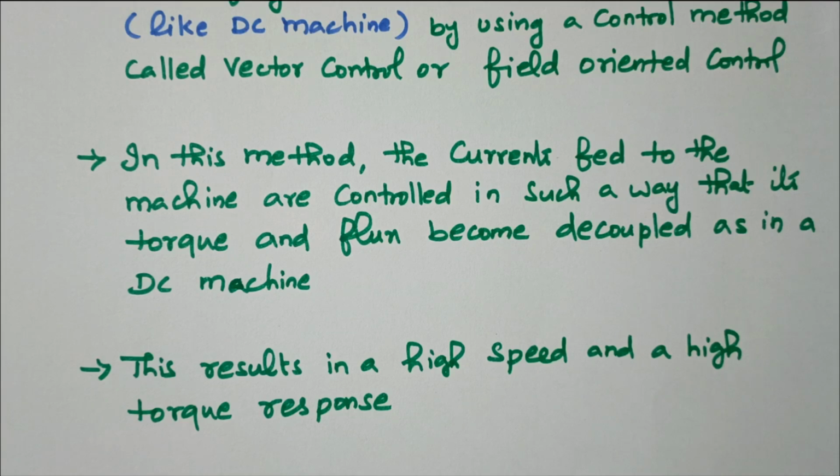So in this video we discussed the AC servo motor. We know that a servo motor is used for control purposes, position control, not for continuous rotation. DC servo motor is available, AC servo motor is available. A separate video is available for both. In this AC servo motor, there are two types, two phase and three phase. Three phase is under research. In two phase, we are using the 90-degree phase difference between the applied voltage of the main winding and the control winding, so that we are able to get position control.